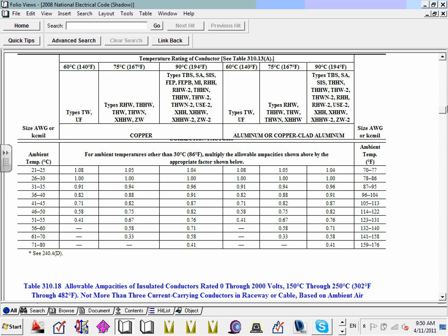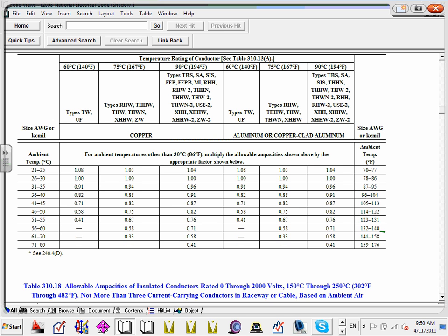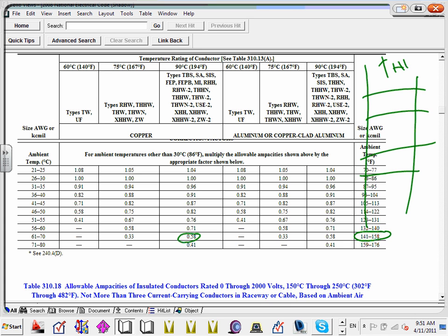Suppose my cable tray was 150 here, and my derating factor is 0.58, because in the cable tray that you guys have seen, I use a THHN, which is 90-degree, so my derating is 0.58. Still the same derating. Cable tray, temperature, same derating. Bundling is different. Temperature, same derating. So really the same derating in terms of temperature, Mr. Bell.